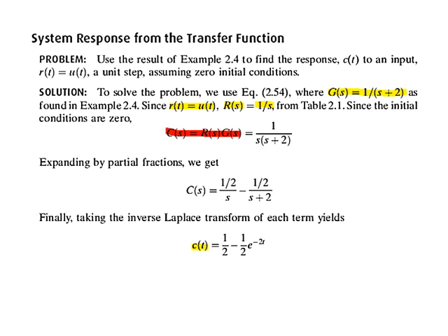But unfortunately, we won't find any relevant form. So we'll use partial fractions and convert the relation of C of s into an appropriate form from that table. After partial fractions, we have reached the equation half multiplied by 1 over s minus half multiplied by 1 over s plus 2.